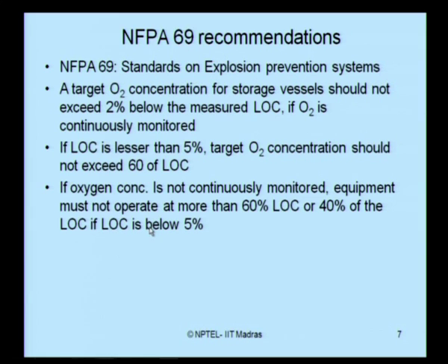If your LOC is below 2% and you are continuously monitoring oxygen, then it should not exceed 60% of LOC. If you are not continuously monitoring the oxygen concentration, and your LOC is below 5%, then it should not exceed a maximum of 40% of LOC, and so on and so forth.